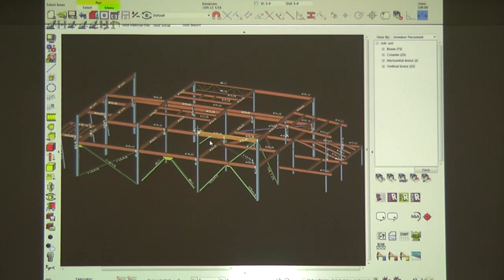I'm going to show you next, basically, what the steel erector would use the SDS2 model for. And again, it's another example of interoperability where this model is used for not only manufacturing the part, they created the drawings, the structural steel detailer created the drawings, they exported information to the CNC robots. Now we're going to go put some cranes in here to use this model on the job site to make sure that everything that we're building can be erected safely and lifted given the crane that they have.